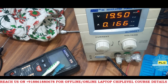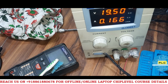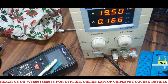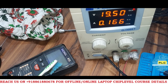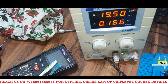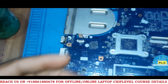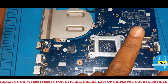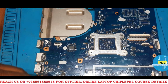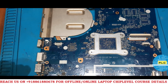So before, when we had that graphics core, I mean the VGA core, and this one, the VCC core, at that time it was 0.179 or 180, right? So now it decreased to 0.166. Okay, now I'm going to remove one more section. So now we removed the VCC core and GFX core 2 part. Okay, now the next position I'm going to remove and then we will check what the amp rating is.